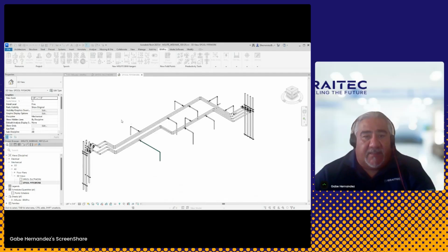I've got some other ones in here as well that are mine, but these custom ones are typical of what you would want to start with at least, and then kind of customize from there, right? Or like I said, use your own. You can load new title blocks here with the browse. You can also set title block parameters. So you have your source and then your target on the title block itself, and you can set those up correctly and reset it if it's not actually working.